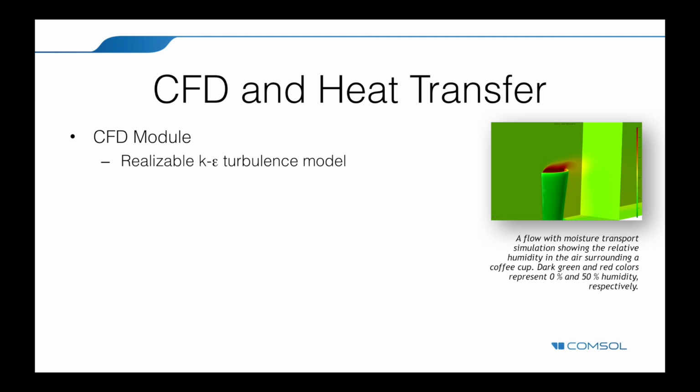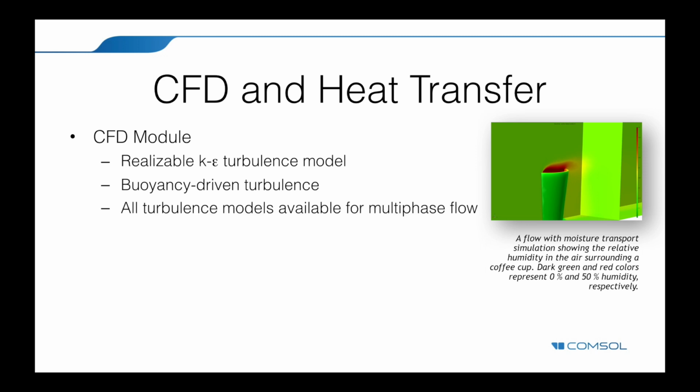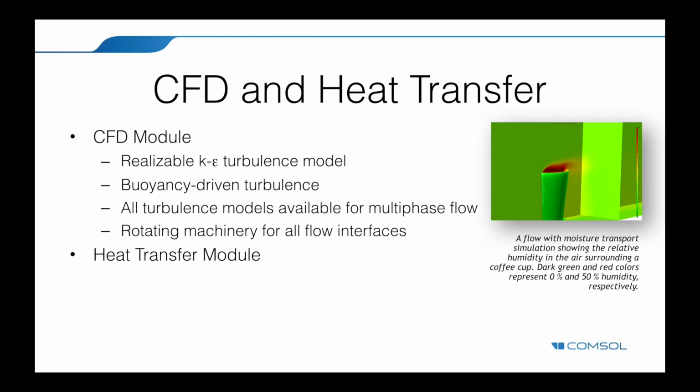CFD and Heat Transfer news. There is a new realizable K-epsilon turbulence model, so now you have much more sophisticated models in the turbulence models section. In both the CFD and the heat transfer module, buoyancy-driven turbulence is now available, and all turbulence models are now available for multi-phase flow, and rotating machinery is available for all flow interfaces. That's a huge and big request that we got over the past years.